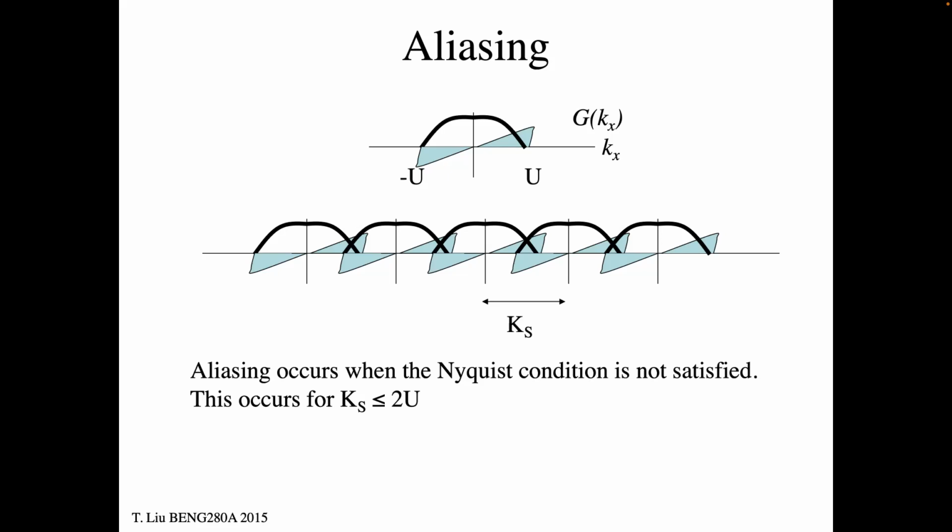What should you do? If you have the option, you should go back and sample it again, right? Just try twice as many samples. And then maybe these will spread apart and you won't have this corruption. And if that doesn't work, try 4 times as many samples. So nowadays, because digital stuff's cheap, you just keep sampling at higher frequencies. The other thing you can do is, if you're stuck with your sampling grid, before it hits your sampling grid, maybe you should filter it, right, so that when it hits your sampling grid, it's inside the Nyquist criterion, right?